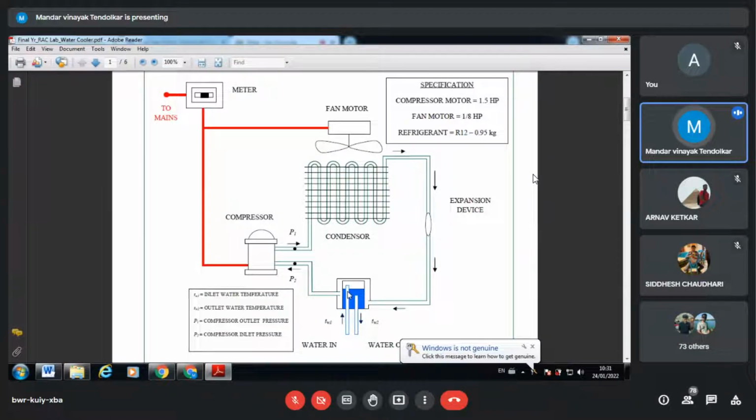In the very same way, for water at 1 atmosphere, you will find from the steam table that 1 atmosphere means 2257 kJ per kg, HFG. How do you find it out? You read the steam table. So same logic, refrigerant table. Instead of steam, meaning water, H2O, it is another kind of working substance, any refrigerant. The moment you come to know the evaporator pressure, or even the working temperature, we will find its corresponding saturation values for the enthalpy of the liquid and the enthalpy of the vapor phases. And the difference between those will be our HFG.